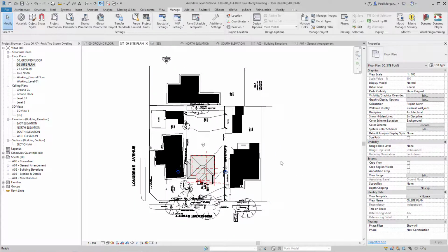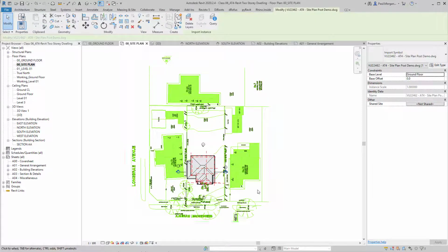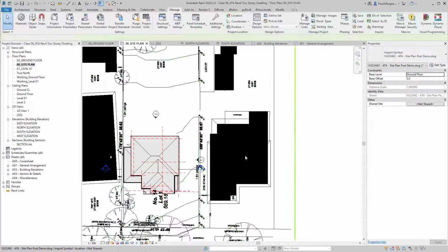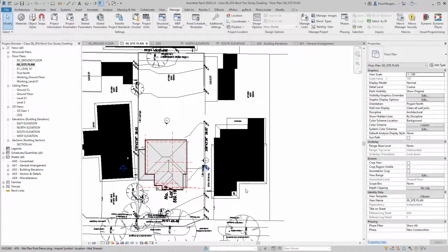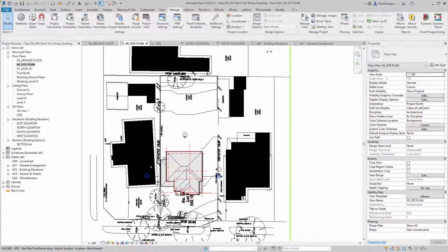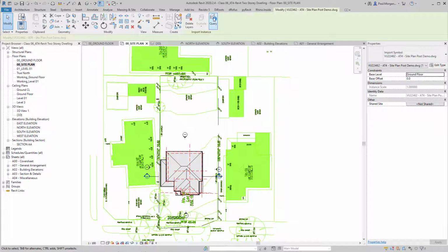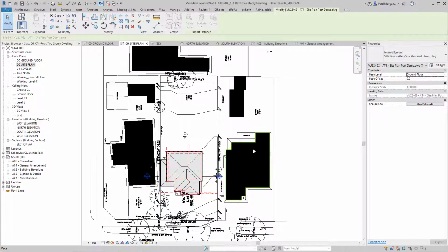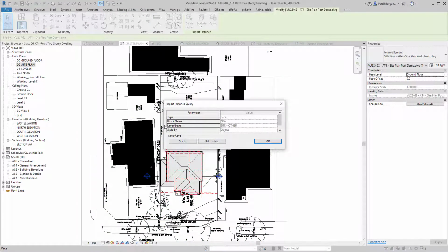then load it back in, and I'll show you how to edit that. So you can edit certain items in here. So let's take, for instance, I click on the drawing and I want to see the roof line. This black hatch is not really appearing quite nicely for my liking. So I click on the survey drawing, and then I click on query, and let's say I just click on that hatch. I click on the hatch and it says the layer is site-other.